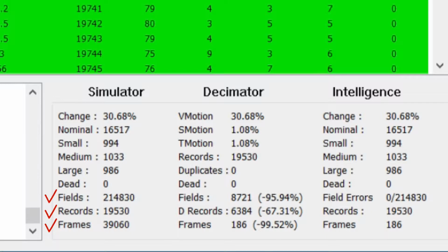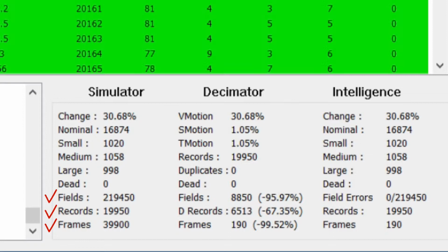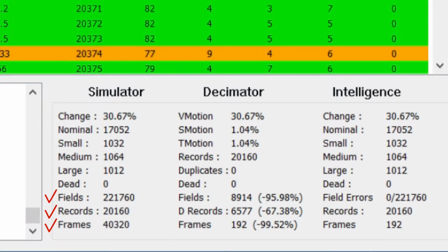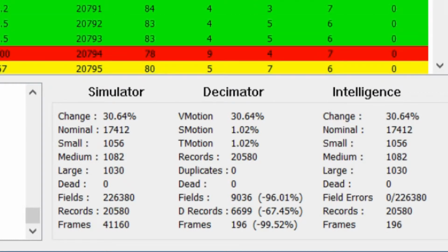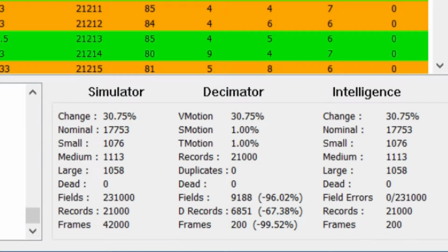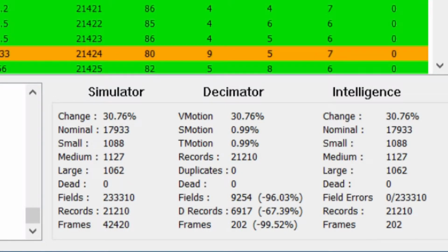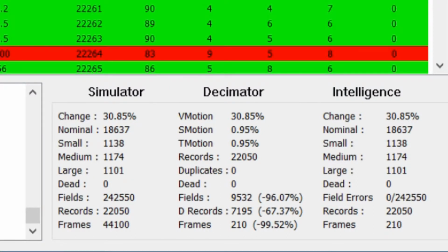A sensor reading is stored in a single digital record, and inside of that record are a number of data fields. Each of the fields holds a piece of information. This information will include the sensor reading and may include other things like identification, timestamps, sequence numbers, location codes, just about anything. The number and types of data fields are based on the data protocol being used. A data record is eventually encoded on a network frame and then is ready for transmission.